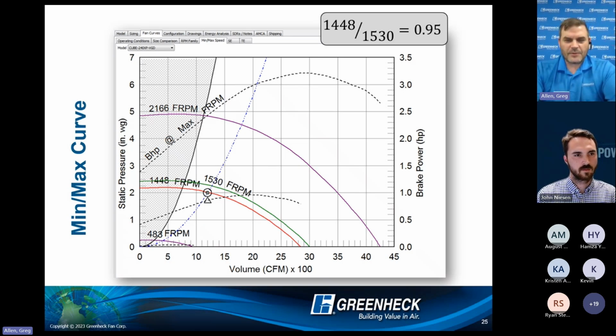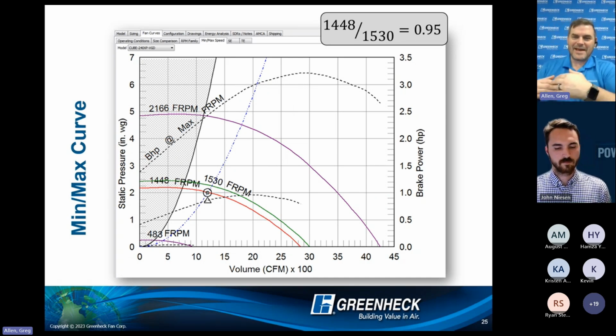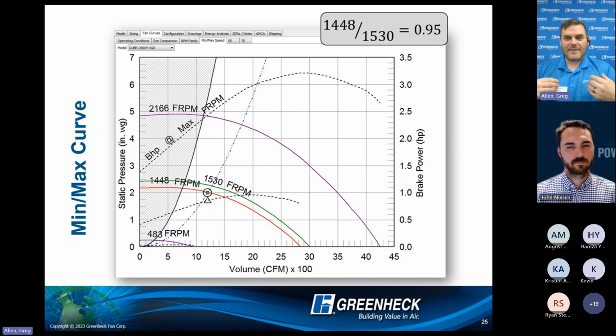But this opens up a controls theory that I can employ. There are products like what I would call a Hand-Off-Auto, or HOA. A simple little box that gives me two points of operation, or the ability to put it in hand mode and define the speed. And then I have an override speed. If a carbon monoxide alarm goes off, I have a simple control that can give me on-off and set different speeds. If you're only killing power and turning power on for this fan, and you just want to set it at one point, a dial is a nice way to go.